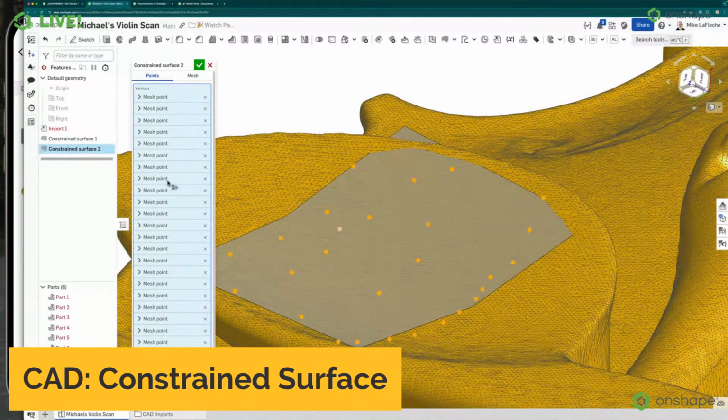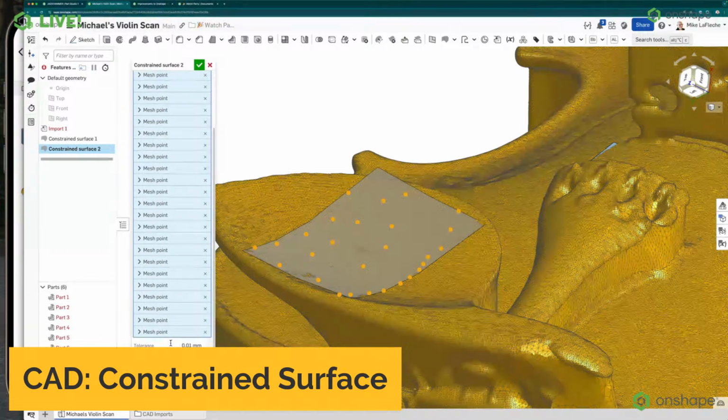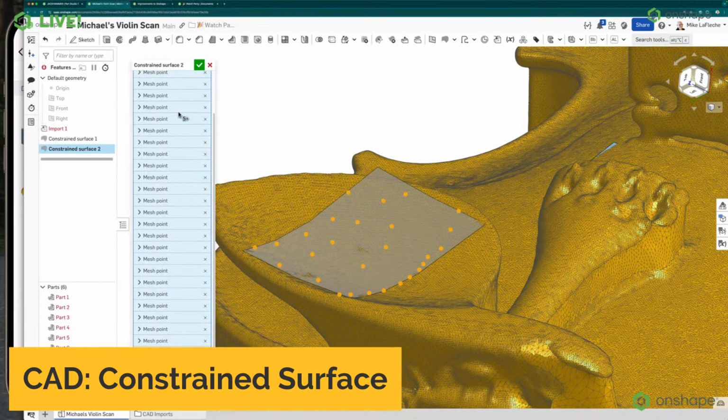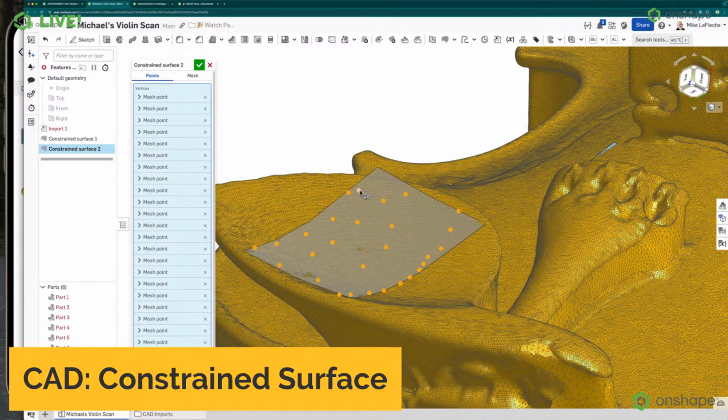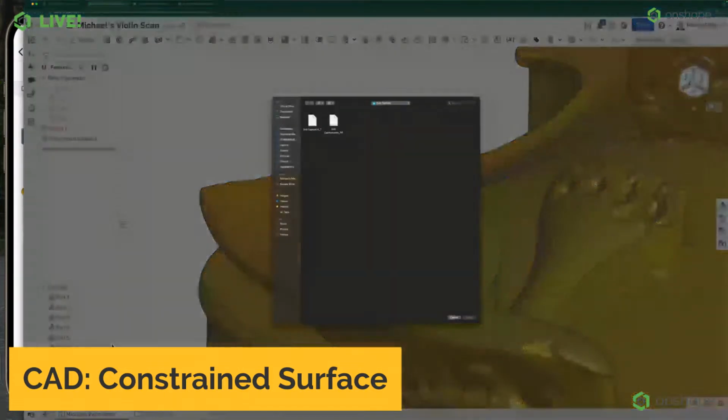This is creating proper BREP surfacing in Onshape, and it's doing it with a tolerance of 0.01 millimeters. There are two different optimization algorithms here that you can choose from: smoothness or performance, right? You can even show a deviation plot against the original. And that's just selecting a bunch of points on the surface. But you could select an entire mesh as well, right? So I think I have some meshes that are simple enough to do this with.